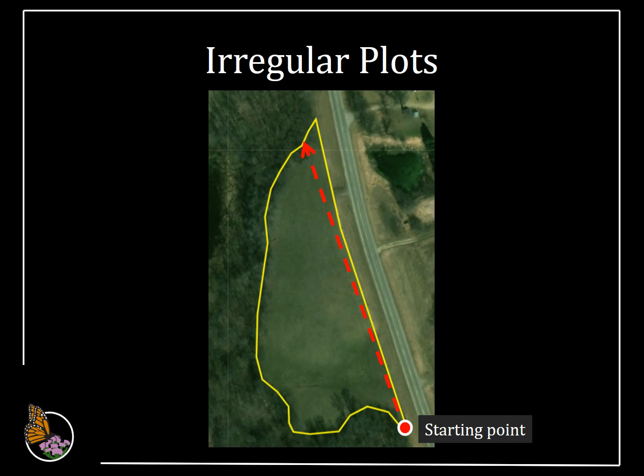When running out your transect tape, you'll want to anchor down the end or have a partner hold an end and walk with the tape until it is fully laid out. The transect tapes only measure 100 meters, so you may need to run it out more than once if your site length is longer than 100 meters. When you reach the boundary of the site, stop putting down subplots.